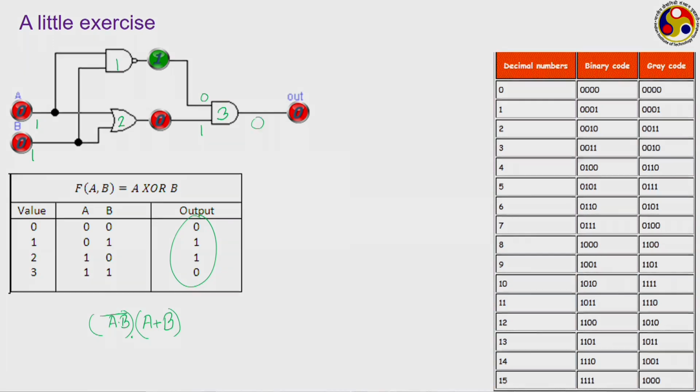Let us take a random number. Let us say we have the number 783 in decimal. We can always convert this to binary, but our objective is not to get the binary version of this, rather we want to get the BCD version, binary coded decimal. What is the idea of BCD? There we have to identify the binary equivalent for each of the digits.